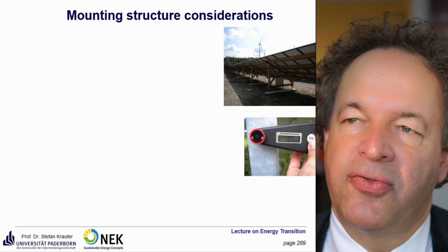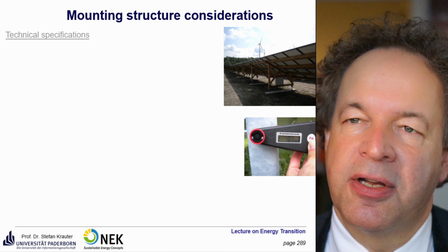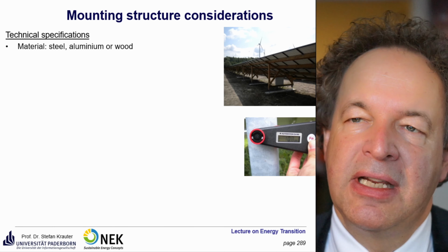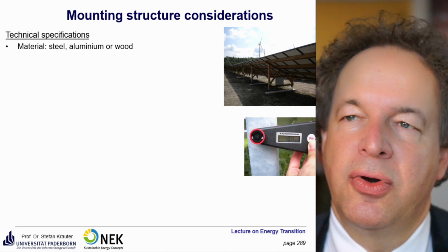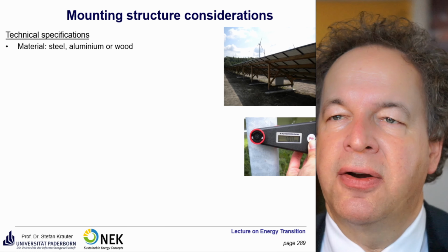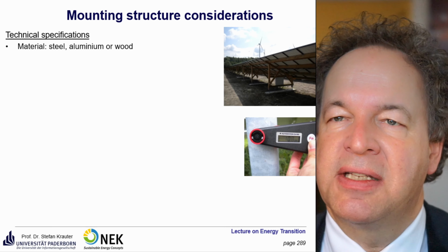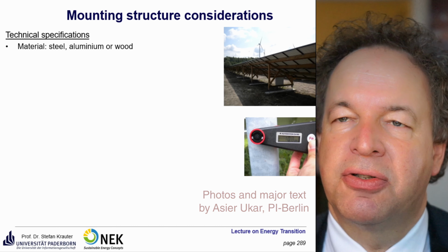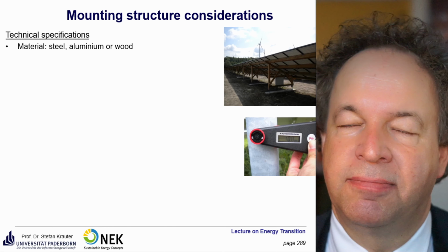So what do you have to consider at the mounting structures? So you have to know the technical specifications. What are they? So the material, steel, aluminium or wood. Sometimes wood is quite a good option. For example, if you go to marine areas which have a salty air, and this is very aggressive to metals, but not so to wood. So sometimes the wood is a longer lasting option than the metal construction, but it depends really on the application.